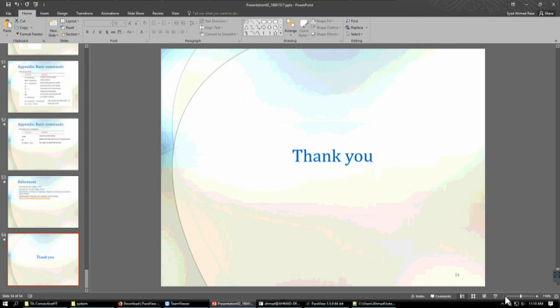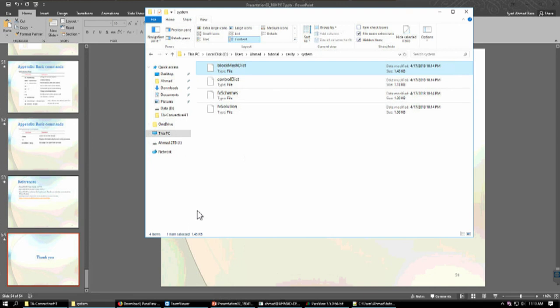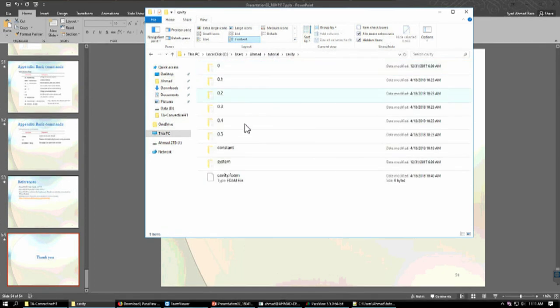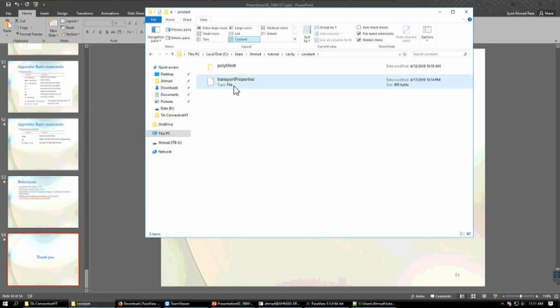Okay, so perhaps you should consider the Reynolds number, such as 100. Through the definition of viscosity, you can define different flows with different Reynolds numbers. So you can fix the geometry and just change the viscosity. Then you can define a flow at the Reynolds number 100.